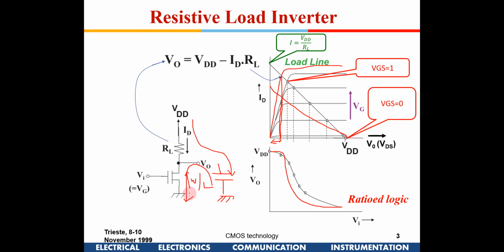Size and area. Yeah, size. More than size. Always think in terms of power and delay for digital circuits. It'll increase power. Yeah, see, this is known as static power. To maintain it low, this transistor continuously remains on. So this is the drawback. When the input is high, current is continuously flowing from VDD to ground. So there is continuous power dissipation in these circuits. That is the reason that by increasing W by L, we have an issue with the power.